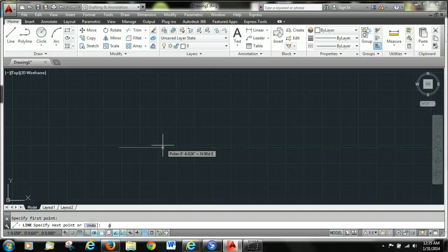And so for this example, I'm just going to do 70 feet. But the drawing that you'll be doing will have specific examples that you're going to give. And then you're going to say angle, and you're going to say north or south, depending on the example that you're working off of. And I'm going to say 45 for the degrees, and then do a D for degrees. And then I'm going to do the minutes and seconds, and that is, in this case, going to be 0 minutes, which uses the foot symbol. And we'll say 0.5 seconds, which uses the inch symbol.